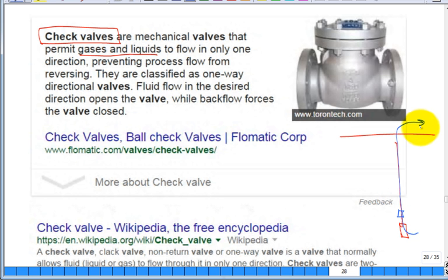It would go into the system, but then when it would stop, it would tend to drain the whole thing. And then it turns on again. You've got to fill that pipe and push it up and out. No, they're going to put in a check valve. So the pump stops, and the head of water sits there waiting. And then when it turns back on, it pushes it out. There are check valves all over the place in very practical situations. But they're very simple. They just stop the backflow.